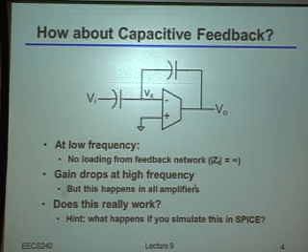What would SPICE do? Yeah, exactly. It would basically come back and say, sorry, convergence error, no DC path to ground from node VX, right? So what's the problem? Why? And by the way, SPICE is absolutely correct in this case. So what's the real practical issue? Why, if you built this circuit in reality, would it actually not work, just like SPICE is basically telling you? What's the problem?